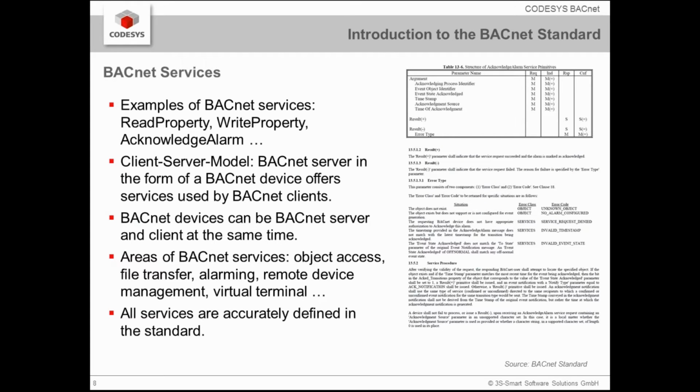Additionally, the standard defines so-called BACnet services. Examples for BACnet services are, for instance, a read of a property, write property, or acknowledgement of an alarm. BACnet services are based on a classical client-server model. So a BACnet server in form of a BACnet device offers services used by different BACnet clients. And a BACnet device can be a BACnet server or client at the same time.